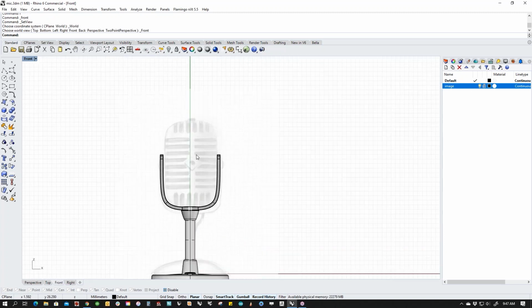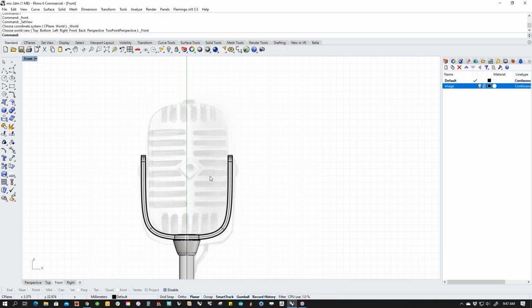All right, so now let's get to the star of the show, which is this. And we have to decide how to do this. There's a couple of ways that we could get there. We could do a rail revolve. Or we could make a profile, extrude a tube, and then try to figure out how to make the caps and stuff like that. But I think what I'm probably going to start with is I'm going to try and do this with blend surf, and we'll see. This might be a mess, but we'll see.